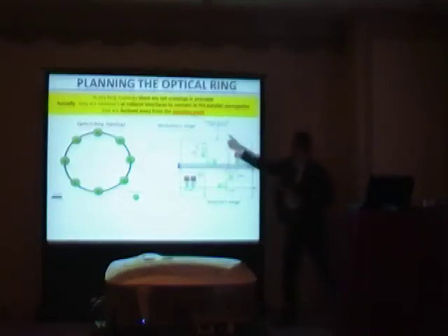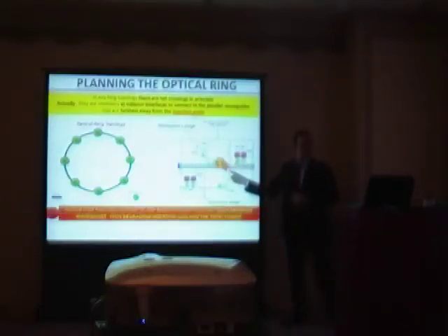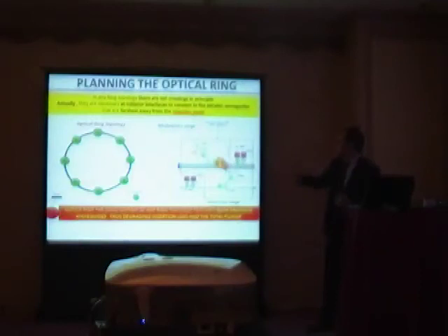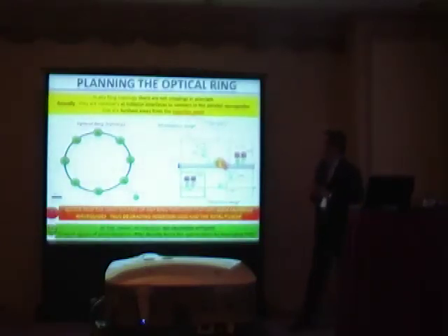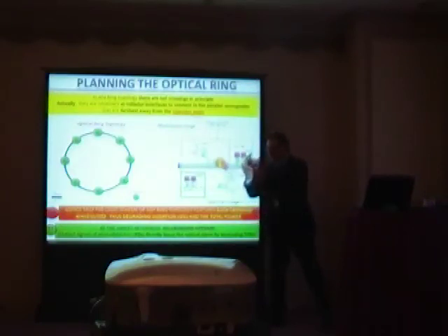In fact, when you have to connect the injection point to the furthest transmission side, here we have the crossings. And these crossings work like obstacles that increase insertion loss and the total power. Instead, at the target interfaces, no crossing appears because the optical power is immediately collected by the photodetectors, and the optical power goes down by using TSVs to the underlying electronic layer.